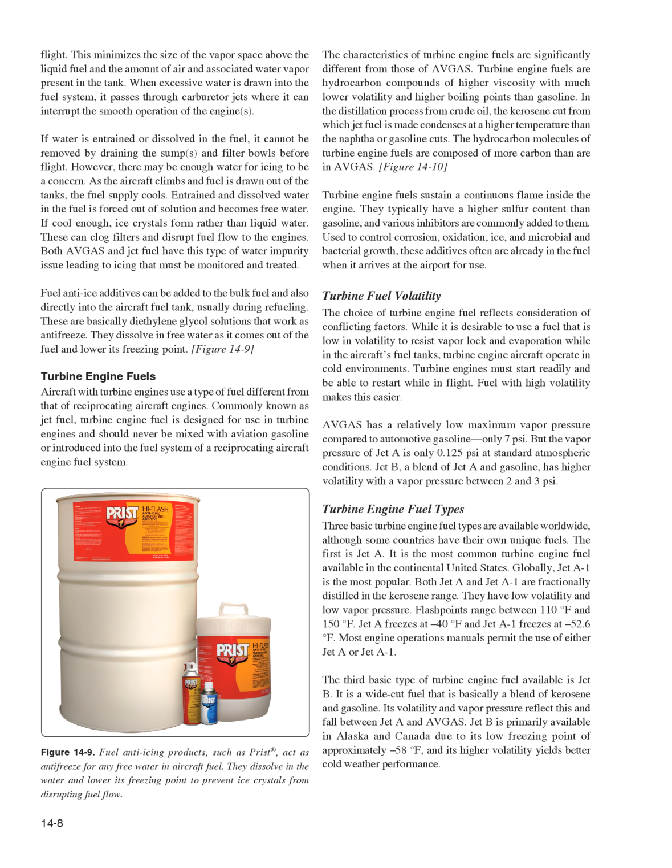Both avgas and jet fuel have this type of water impurity issue, leading to icing that must be monitored and treated. Fuel anti-ice additives can be added to the bulk fuel and also directly into the aircraft fuel tank, usually during refueling. These are basically diethylene glycol solutions that work as antifreeze. They dissolve in free water as it comes out of the fuel and lower its freezing point.